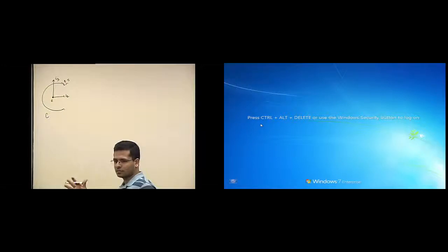They are not Cartesian coordinates. So let's assume that this is a centroidal reference frame, which is at the principal axis of bending. So I2 and I3 are aligned with the principal axis of bending, and as you can see, when S moves along the curve, x2 and x3 change, so they do not remain constant, or they do not have a particular value along a line.